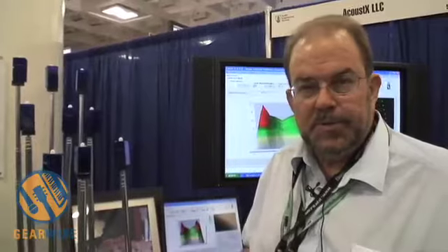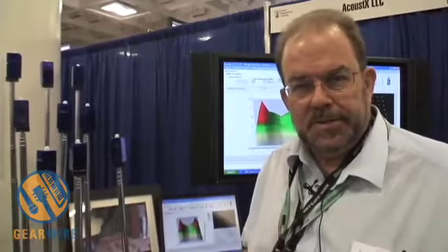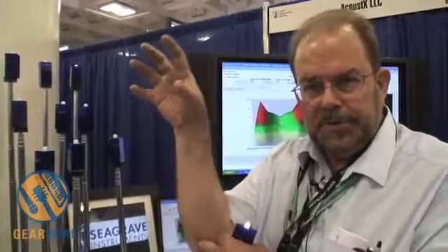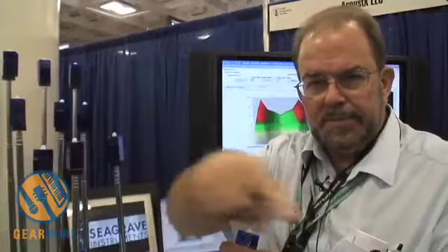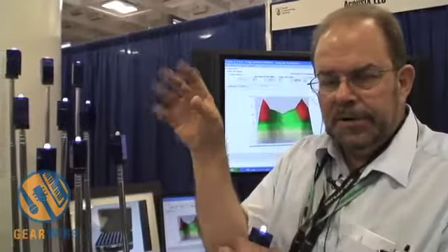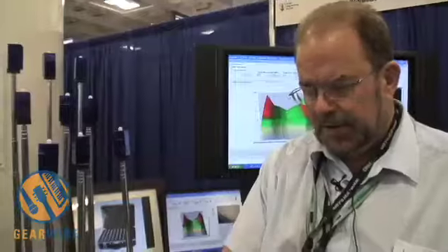The system is also used for setting up PA systems. Directional loudspeakers will be loud in the center perhaps and a little less on the sides. Here, instead of a guy with a sound level meter saying, "It's a little low over here, Joe," you can actually have the sound level meters showing the light and the amplitude all at the same time. So you set up maybe 49 sensors out there in an array, and you can actually point the loudspeaker and see where its coverage pattern is in real time.